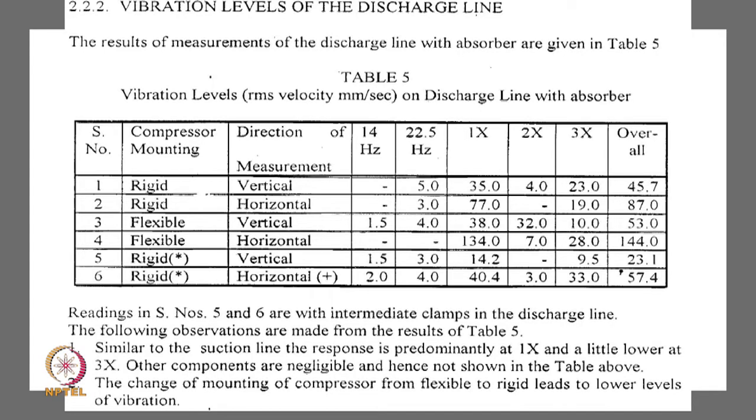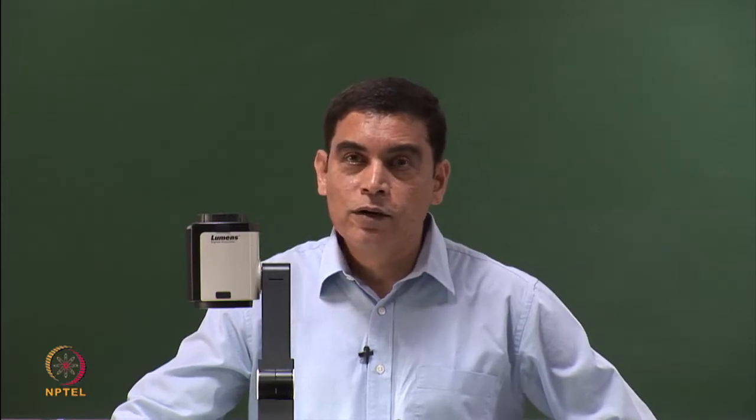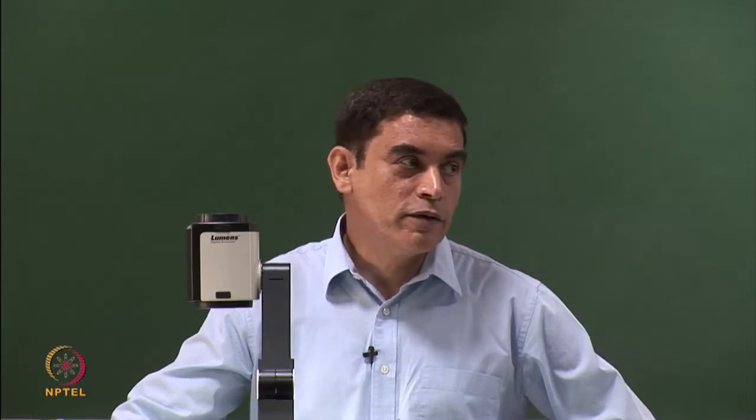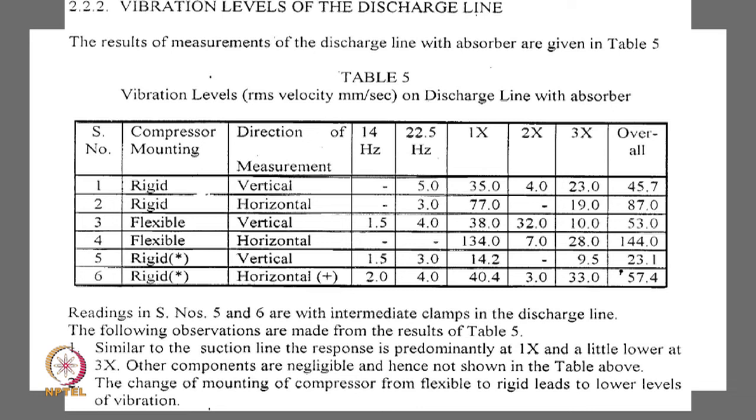Now in the absence of any standards, the values of vibration levels have been used only for comparative purposes. The values also established that the compressor is the predominant source of excitation of the tubing. And here again, when it comes to design and when you do not have standards, we did not know what level of excitation is acceptable. We had to look at comparison and look at something which was going to make a significant improvement from our status, which was resulting in failures. So we used it more as a reference, as a guide as to what a design change would do.